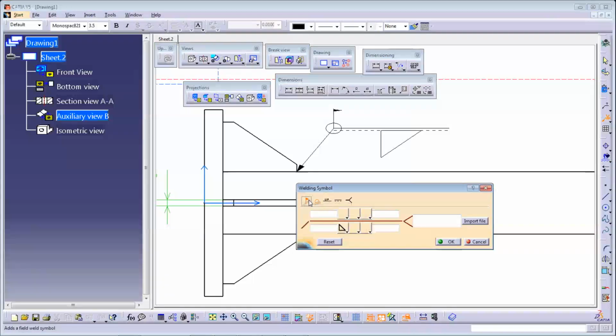What is the meaning of this flag? Sometimes in an interview it may be asked. The flag indicates that you have to weld the component in the field, that is, at the installation site. Do not weld directly in the workshop. If you turn this option off, then you have the freedom to weld the component in the workshop and then assemble it in the specific location.